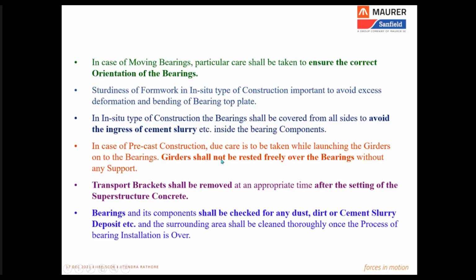The girders shall also not be rested freely onto the bearings because bearings are the device which by virtue of their own design itself are offering resistance-free rotation. So if we leave the girder sitting onto the bearing without any side support, that is more or less creating a situation of an inverted pendulum. Or in very general terms, it means you are trying to stand on a ball. And it is very difficult to maintain a balance when you are standing on a ball; either you have to topple right side or left side. So the same could happen with a girder also if it is not rested when it is launched onto the bearing.